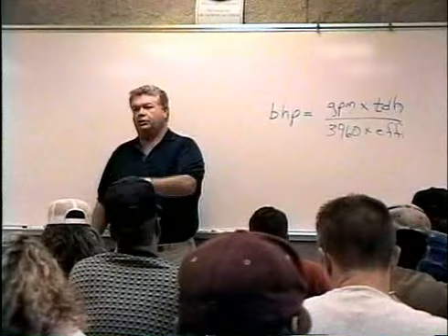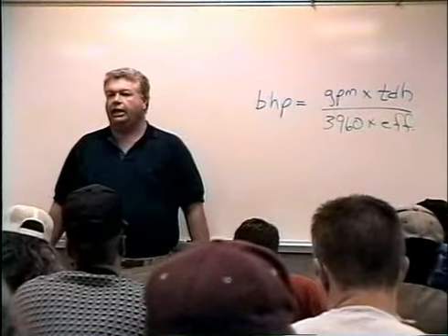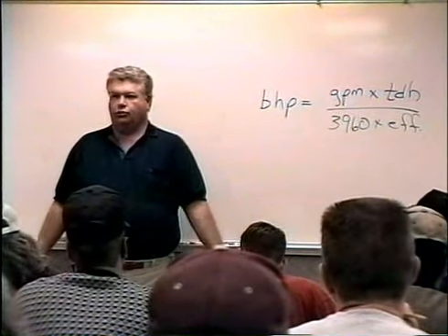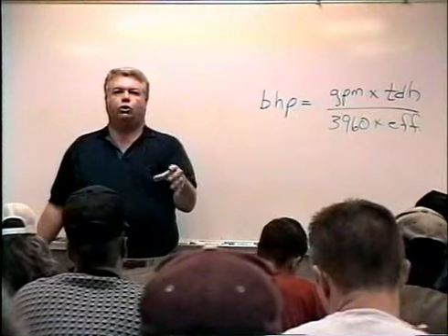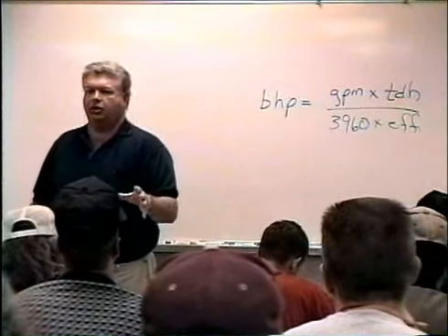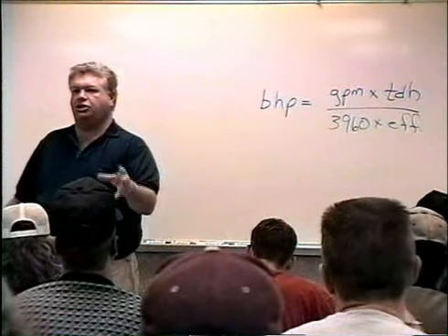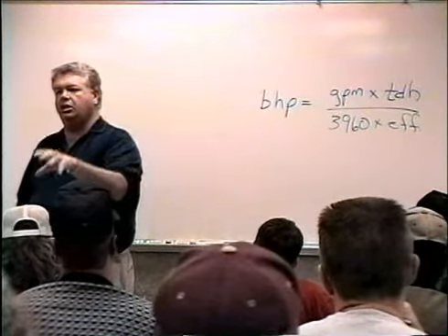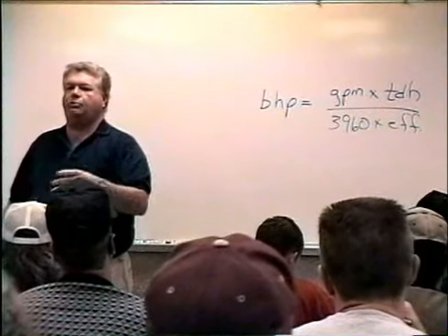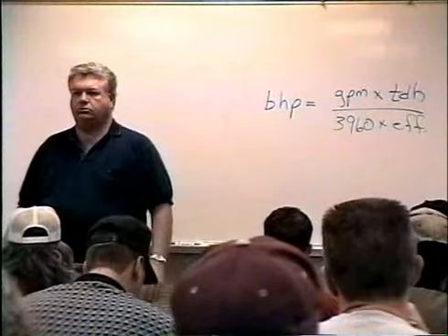We know we're going to run so many sprinklers at so many gallons a minute per sprinkler, therefore it's going to cost so many total gallons per minute. We pick that. That's a given that we give it. If we're going to run the golf course and we're going to run 4 sprinklers at a time and they all run at 40 gallons a minute, we know we need 160 gallons a minute on a continuum. And those sprinklers will be turning off and others will be turning on, but they'll be continuously cycling over the night, and we'll have 4 of them running all the time, and we need 160 gallons a minute continuous for the duration of the cycle.